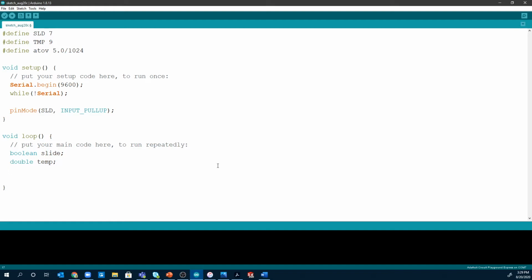We're going to actually have to use both in this case because of the fact that the %f format stream doesn't work correctly in this particular Arduino. So for this purpose, we're going to call a char output by 64, which will allow us to have up to 64 characters in the string. Simultaneously, we're going to create a string that we're going to call T output for temporary output.